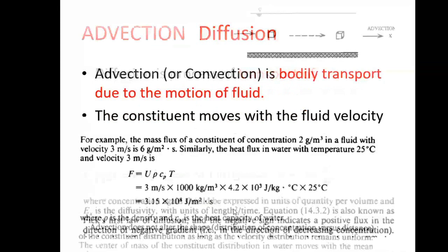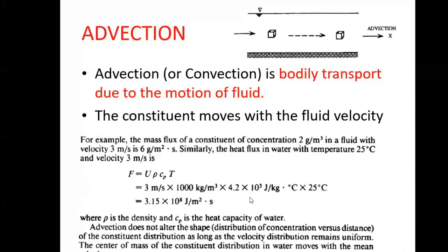Okay, so that is how this concept of flux can be used to see the movement or transport. And for advection, because it is moving along with the flow, flux can be calculated using simply the velocity of the water. When flux is known, it means I can know after how much time it will reach the downstream side, when it will be reaching at what place. This is per second, so this is a movement of the energy per second. So I can analyze advection using this concept of flux, U into C.